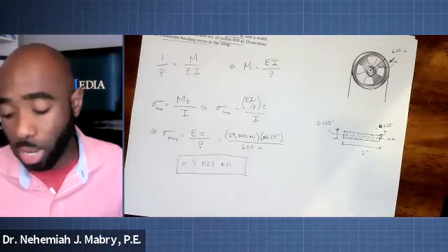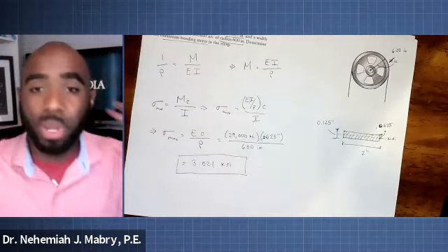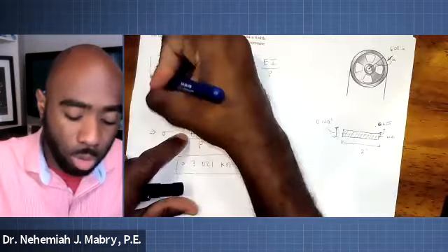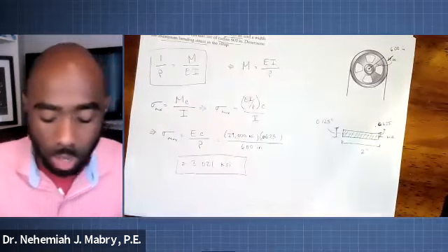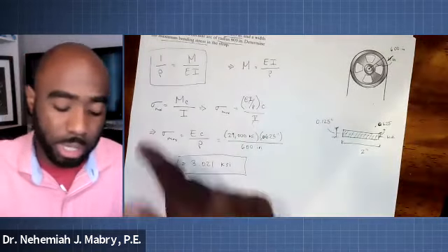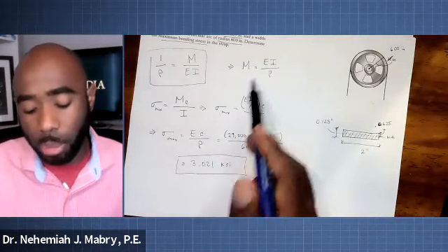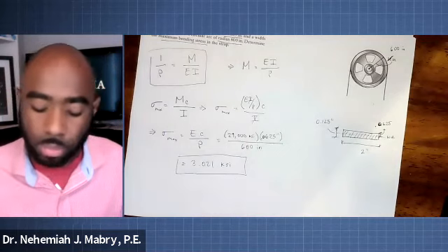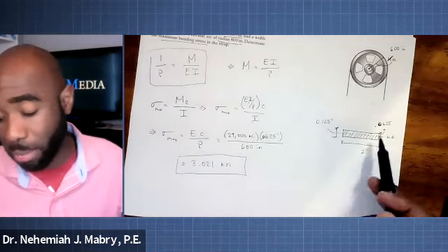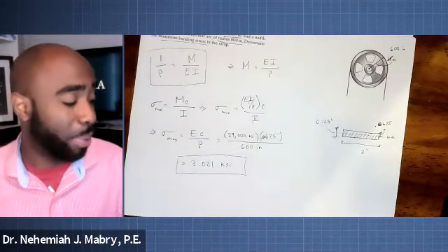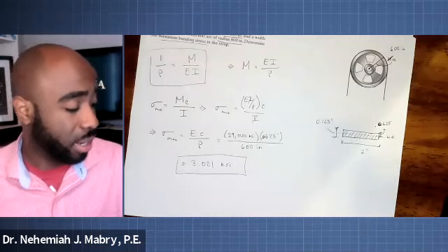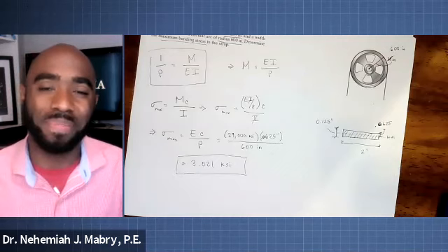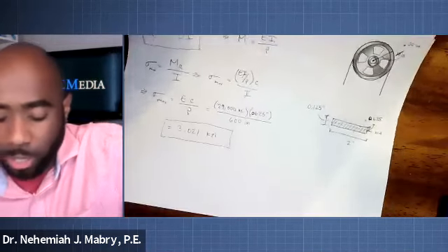That is 12.1. So that is going to be the sole example in this lecture that we'll do with this particular equation. But don't lose sight of what we just did there. We connected to the maximum bending stress by isolating M, plugging it into the bending stress equation, the flexural formula. From there, we made sure our numbers were correct. Make sure you use your decimals in the right place. And then we are able to solve the problem. All right, so let's get back to the concepts.